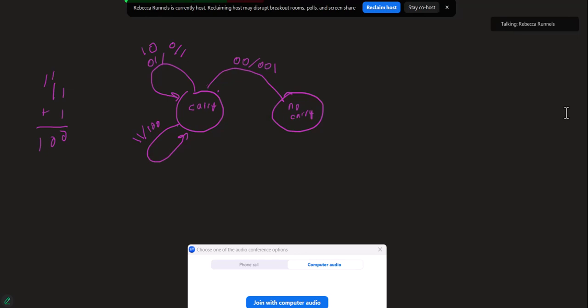That's if I had a carry. If I had no carry and my inputs are 0, 0, what's my output going to be? What's 0 plus 0 plus 0? 0. If my inputs are a 0 and 1 and I didn't have a carry, that'll be 1. So 0, 1, and that would give me 0, 0, 1. If my inputs are 1 and 1, what's my output? 0, with a carry of 1.